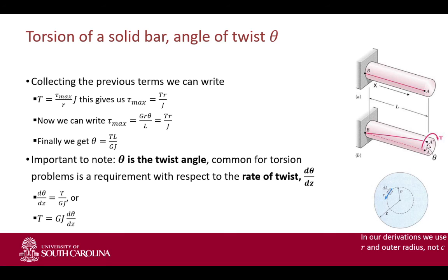of inertia. And the reason why we want to isolate theta and not say torsion is because the angle of twist, which theta represents, can be a design requirement. In many cases, you have to design for given stresses and loads, what we had in the bending case, and in torsion you often have to design for maximum angle of twist.